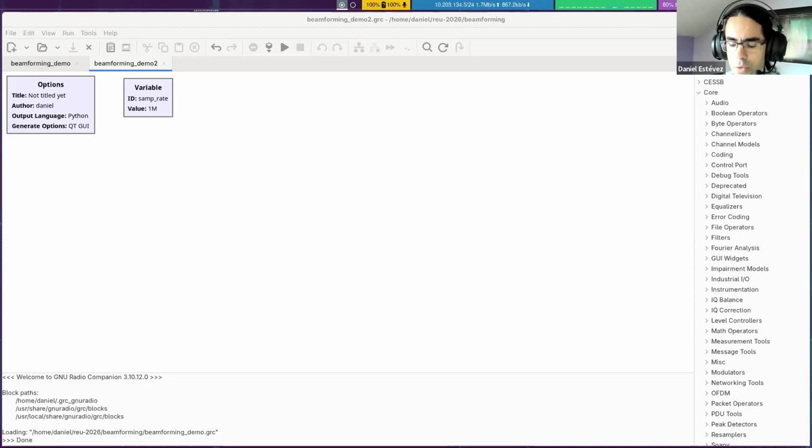Here we are going to generate band limited noise, that is, noise which only occupies a portion of the spectrum, so that it is easy to see the signal to noise ratio. We will be able to see the source in some part of the spectrum and then the rest of the spectrum is the noise floor.